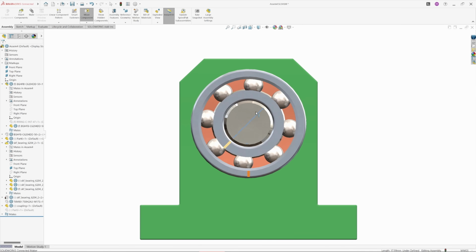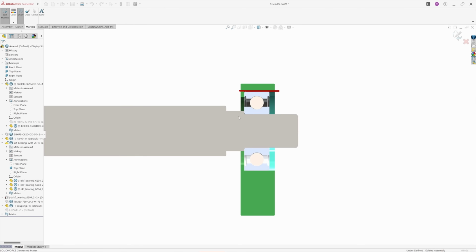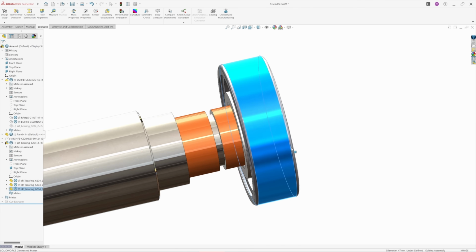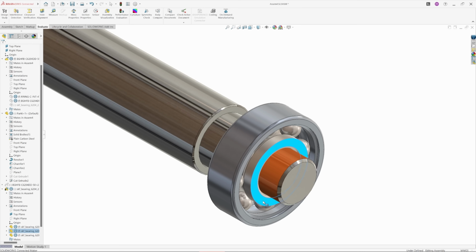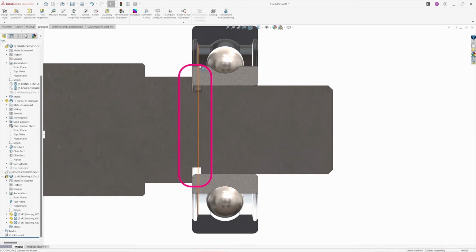To fully exploit the load carrying ability of a bearing, our bearing seat must support both rings of the bearing around the full circumference and across the entire width of the rings. Therefore, the bearing seat has to be manufactured to adequate geometric and dimensional tolerances. Plus, the bearing seat should not be interrupted by a groove or a hole or other features. Do not add any undercut or slot or anything over the bearing seat. The bearing can be permanently damaged under heavy loads.